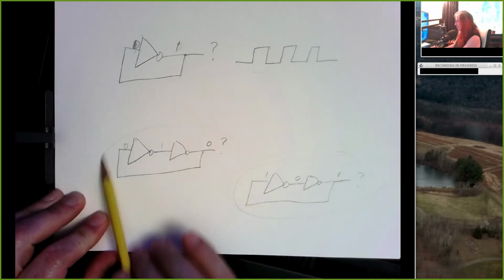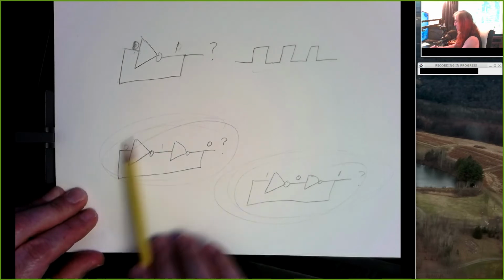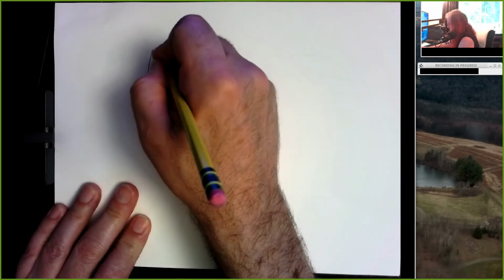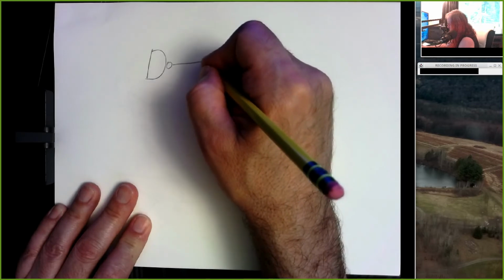All right. Well, having to take a wire and temporarily touch it to the output and hope that your instructor didn't see it, right, is not a great way to use a memory system. So we're going to modify this design just a little bit. Remember, NAND gates and NOR gates can sometimes act like inverters. So let's build this same kind of circuit, but let's use NAND gates.